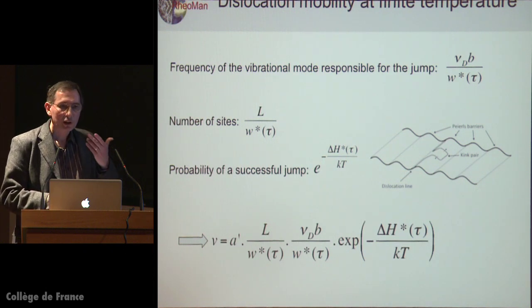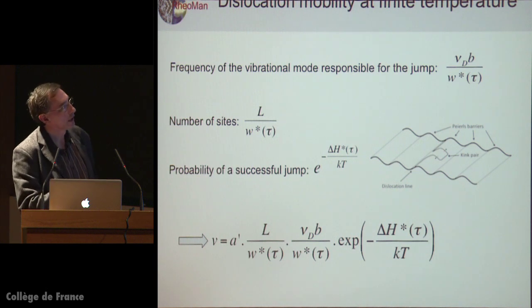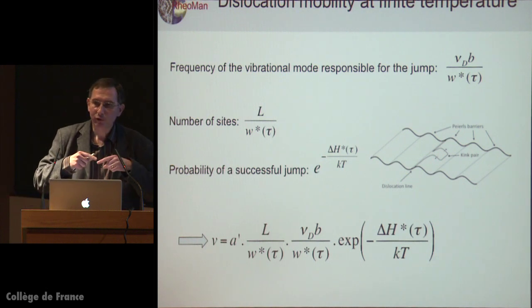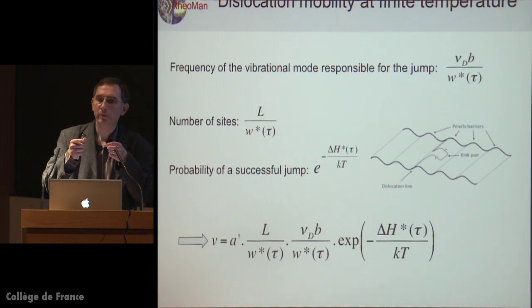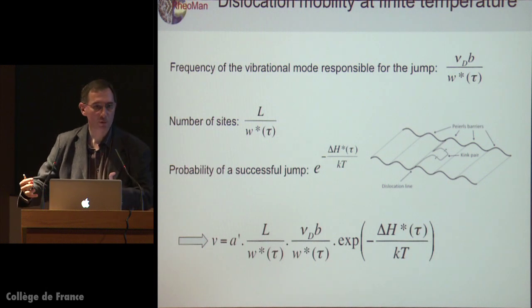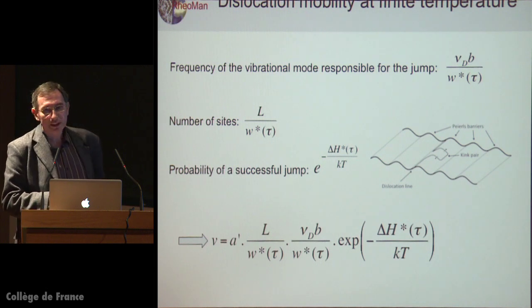So we need to invent some mechanisms by which a dislocation will progressively move, and this is what operates, we call that the kink-pair mechanism. We need to understand how a dislocation line will throw a small loop over the barrier, which will pull the rest of the dislocation, and then the dislocation will have moved by one step. So this kind of mechanism we can describe.